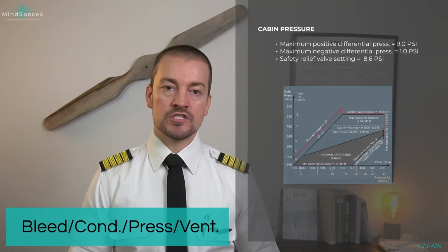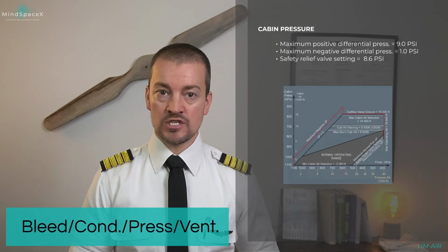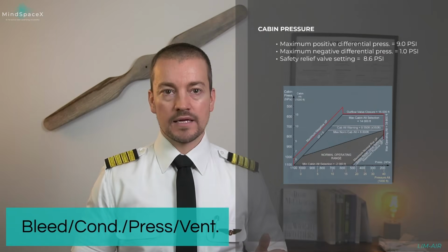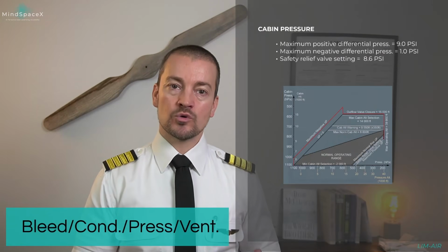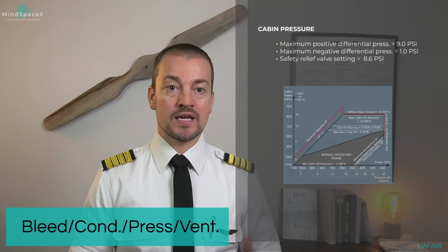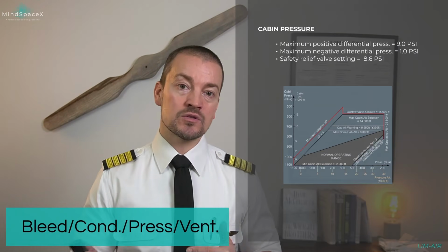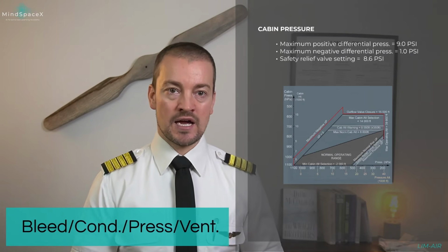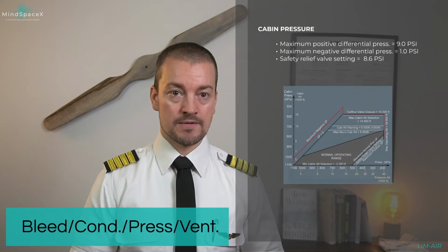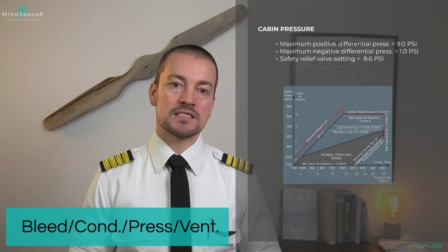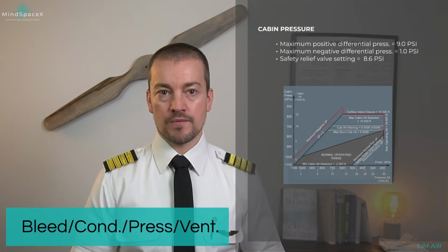The cabin pressurization, as we discussed in the presentation on pressurization, has limitations that are very, very important. The cabin operates with a lower altitude than outside. Because of that, pressure exists between the outside and the inside, with a higher pressure inside the cabin than outside when we operate the aircraft in flight. This means that there is a pressure difference between outside and inside known as differential pressure.